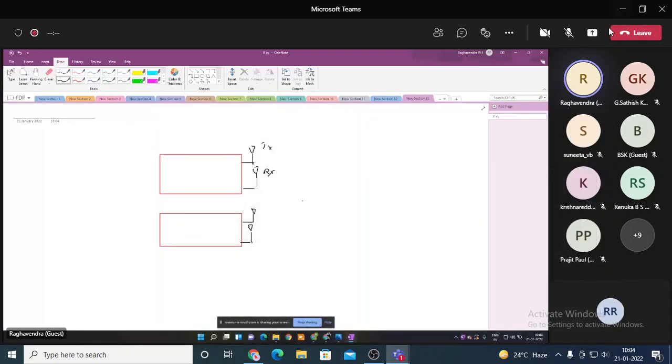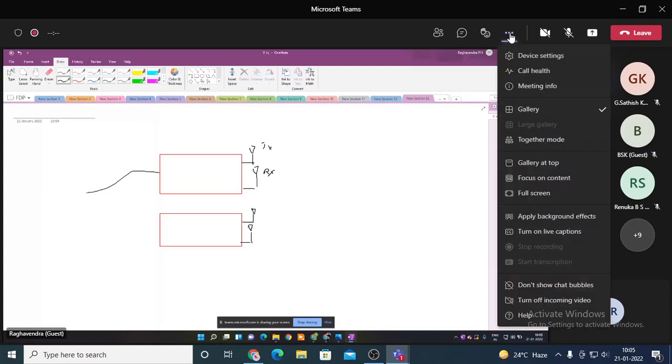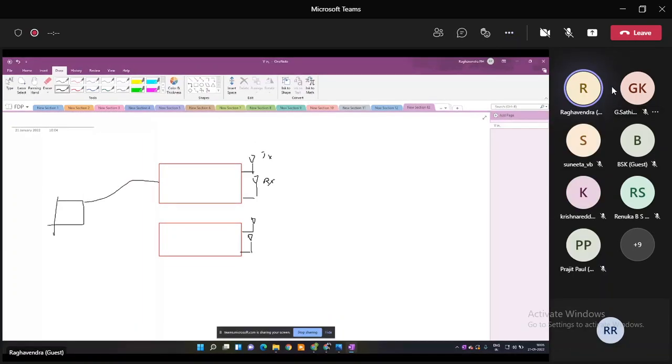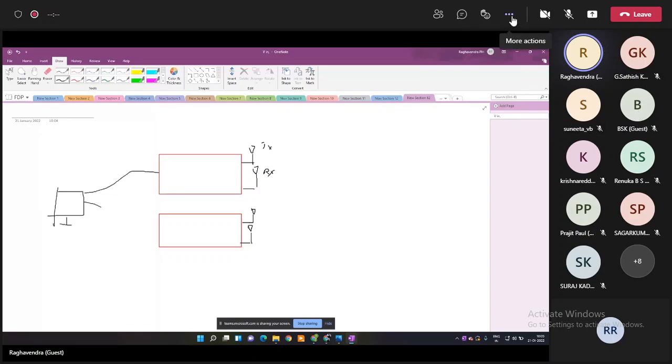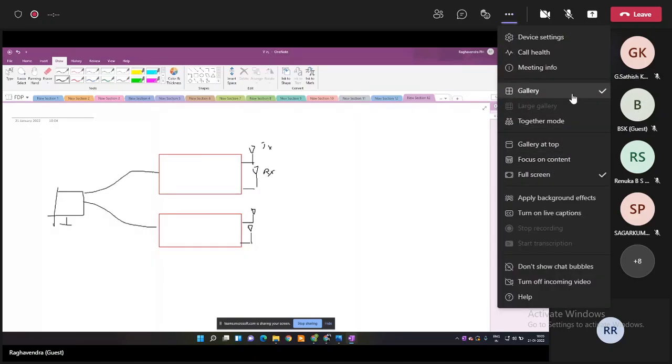different USRPs and each of them have their own individual RF channels, will I be able to do a MIMO on this? The answer is yes and no. Yes, because you will actually be able to connect these two USRPs to a single computer and in fact access them from a single piece of code, and you will be able to send the channels respective information.